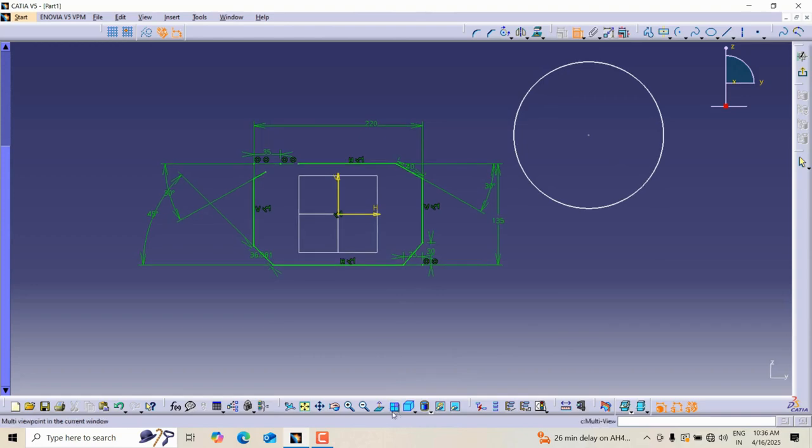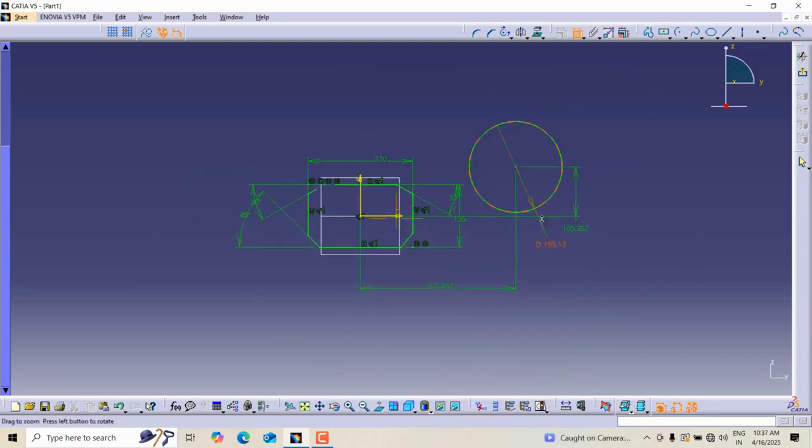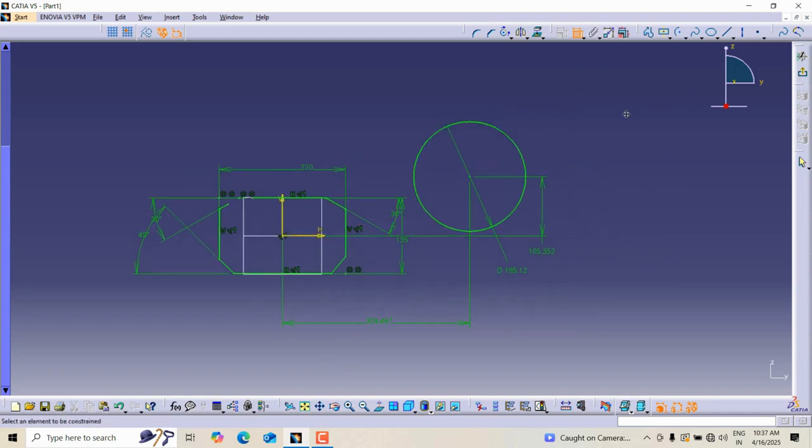If I want to define this circle again, just double click it here. Make this sketch normal first. We have this icon here, we can see in view tab, that is making it normal to. At the bottom side in the center of the screen, we'll select the origin and the center point of the circle, say it vertical dimension first, and then go for the horizontal dimension in same way. Same selections and horizontal measure. Provide the radius or diameter, and here we have this sketch completed as a constraint sketch.